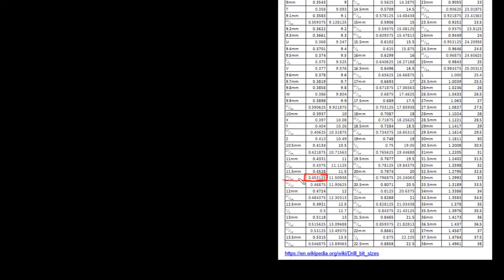These decimals come because a fraction creates lots and lots of digits, whereas you'll notice a Z only has 3, and a millimeter maybe has 4 because of the conversion. If you choose 3 decimal places, that would be a safe bet. You could use a reamer or bore the hole if you want a more accurate hole. So anyway, we're just going to use 0.543.